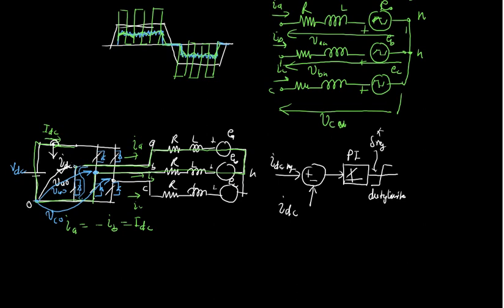So let me make it as it was. Done? So what will happen? This value will be either switch on or off, so 1 or 0. You are going to limit this value to a duty ratio of 0 or 1. So now you have a duty reference, delta reference, here. Now we have to generate the PWM pulses. Remember these pulses? We have to generate them, then only we can operate it, because this delta reference is a continuous value.